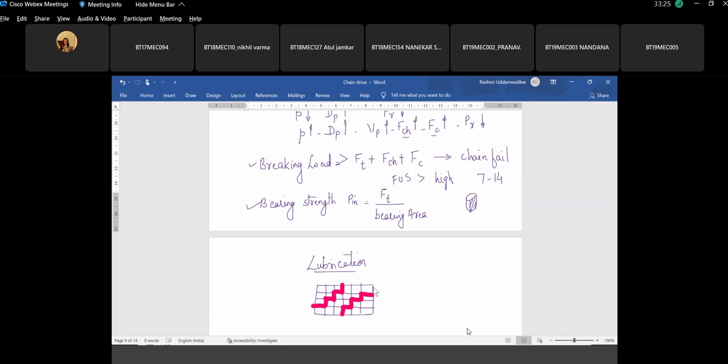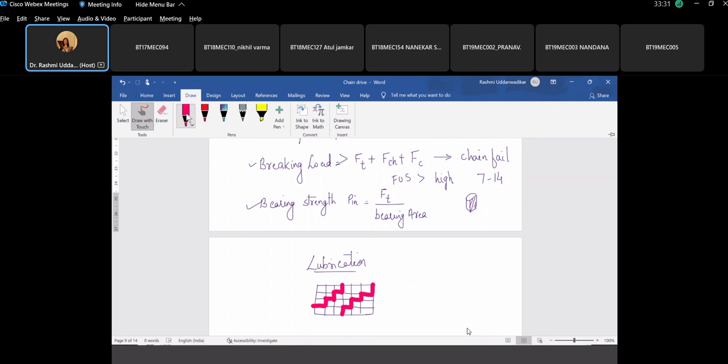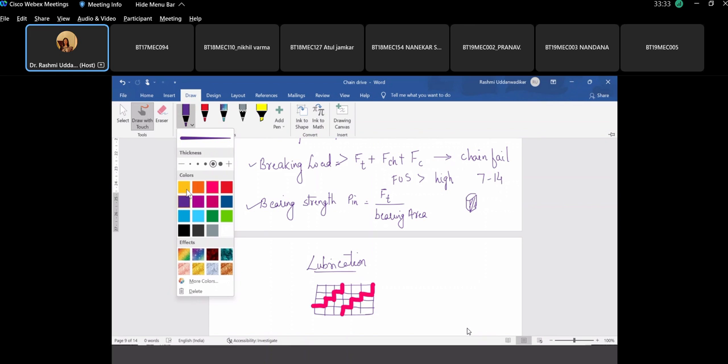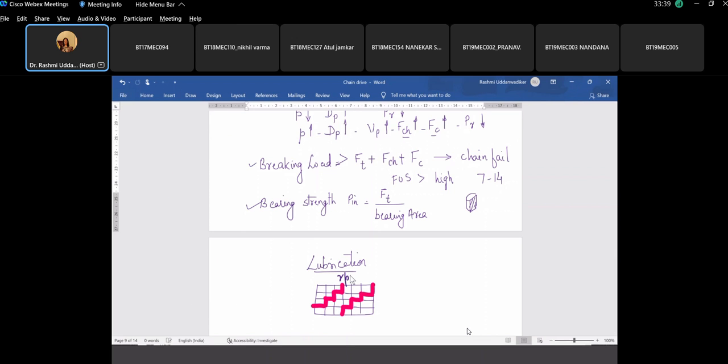These are the bold lines. Class 1 lubrication, class 2 lubrication, and class 3 lubrication are demarcated using these. Here this is indicating increase in the RPM, and the power transmission capacity is mentioned in these cells.